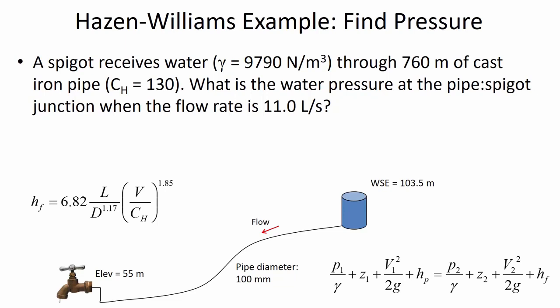And so that explains why when we were doing the first problem, we calculated there was 303 kilopascals of pressure available. Like if you connected a hose to the threads on that valve, and you opened it up and measured the pressure that's available as the water is flowing, it is the 303 kilopascals. But if you take the hose off, then there's zero pressure as the water comes out and is just in contact with the atmosphere. But just on the other side of that valve, now there's water pressure that is available.